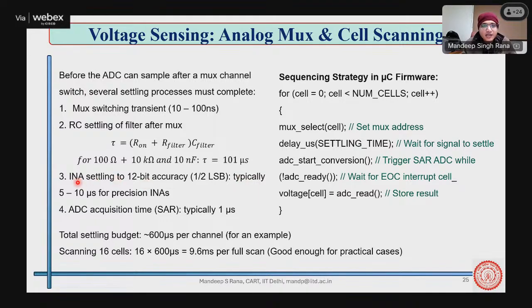Now you have your own 12-bit conversion algorithm for the ADC. It also takes its own sampling time to conversion time. That is something like 5 to 10 microseconds for most of the ICs we generally use, and it takes its own small acquisition time, just to read the data and then convert. So two things are there, it takes some time.